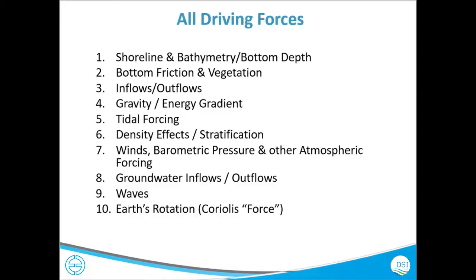And inflows and outflows, this is the most critical part in any hydrodynamic modeling. They say garbage in, garbage out, right? So gravity and energy gradient are related to the bathymetry. If you have your bathymetry, you'll know which is the higher elevation and where the water should flow. Sometimes when you're assigning bathymetry, you wouldn't know it, but there might be some kind of island or areas with higher bottom elevation.